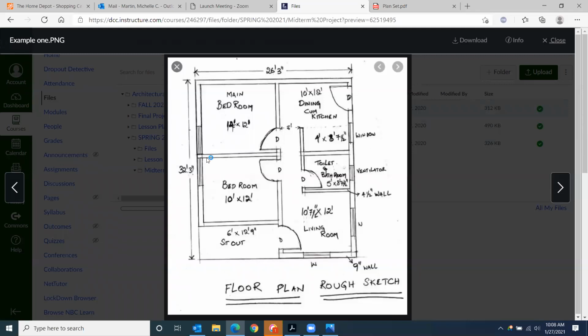And that's kind of like what we're starting out with right here. I mean, we're not actually creating anything new, but we're still, as we start creating these sketches and getting your measurements done and taking these sketches and measurements to Revit itself, you're going to see that there's still going to be some things that you're going to have to figure out. There's things that we don't know, especially when we do this project in class, that we have some brand new construction where your walls are going to be a typical 4.5-inch wall, 1/2-inch gyp on both sides, and a 3.5-inch wood member in the middle.